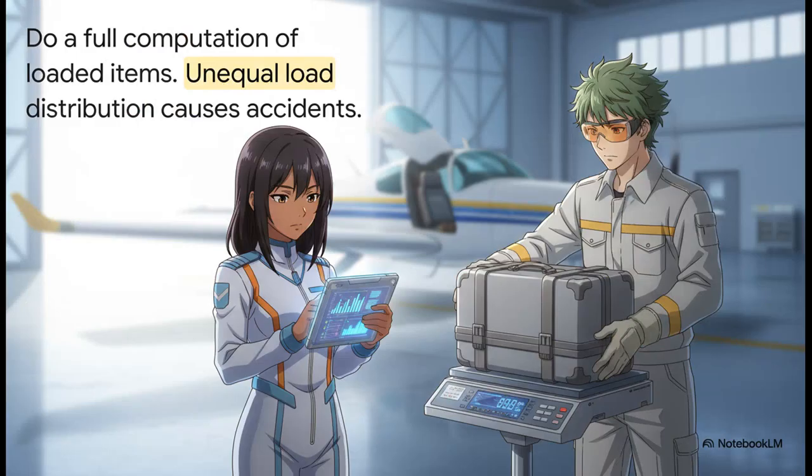Which brings us to a golden rule: compute everything. Unequal load distribution causes accidents. And remember, aircraft weight and balance data isn't valid indefinitely. Over time, planes get repainted, equipment is upgraded, maybe some heavier new avionics are swapped in. Because of all these modifications, you absolutely must do a fresh computation of all loaded items. Don't guess, actually weigh the baggage. Doing the math ensures you're respecting the exact limits of your specific aircraft on that specific day.